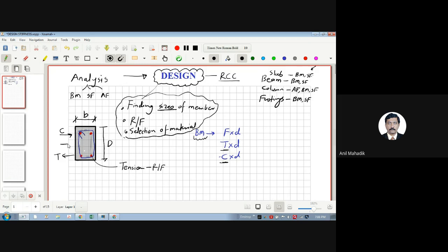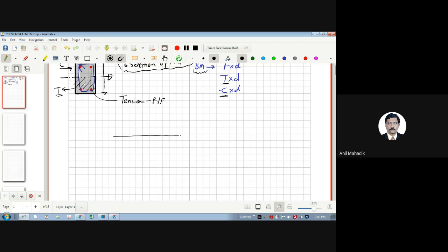Generally there is a neutral axis. Let's say the lower zone is the tension zone due to the bending moment. Then we ignore this lower concrete part, and we provide reinforcement for taking this tension. And the upper part we use for taking the compression coming through the bending moment. If we have this kind of beam, due to the load it will bend.